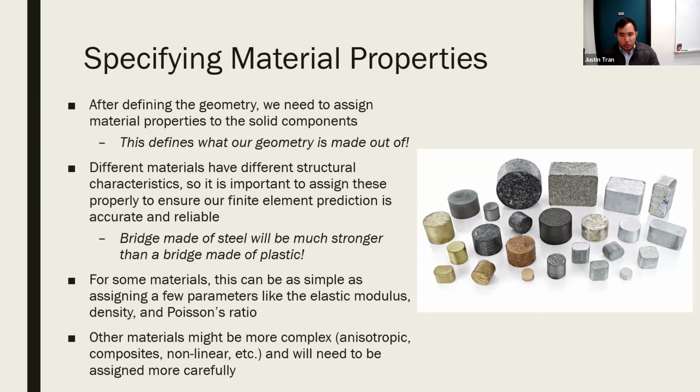So in this class, we'll actually be diving into this quite a bit, because not only do you have to choose the material properties, but different materials will have different behaviors as well. Okay. So I think what most people are used to are what's called linear isotropic materials, which are like most of your metals. But materials like plastics, composites, and wood have different material models as well, where maybe you have to apply different stiffness in different directions, because that's going to affect your results.